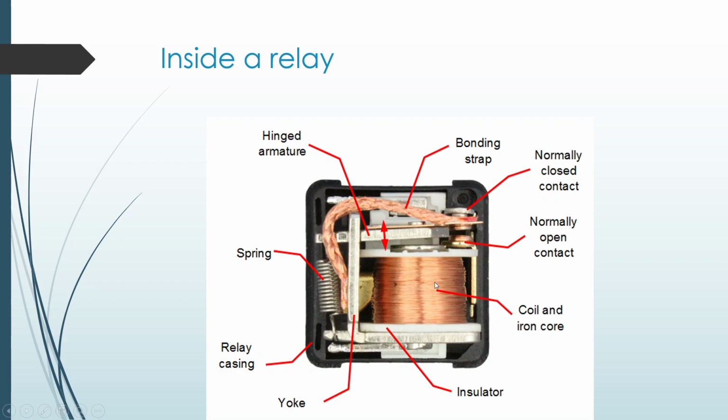And when you energize the coil and iron core, what will happen? This will get attracted. When this gets attracted, it will disconnect from normally closed and connect to normally open.